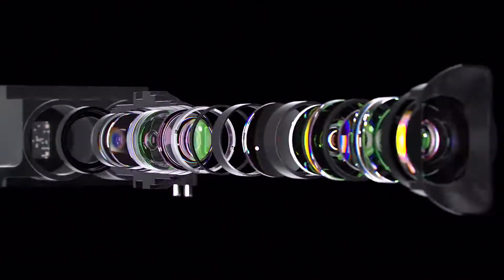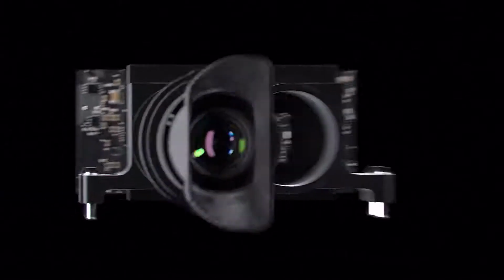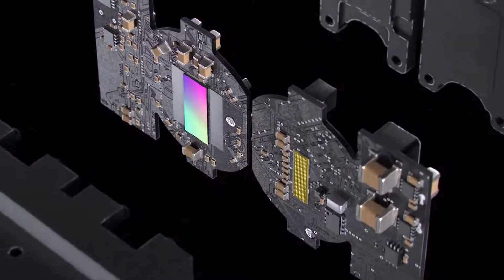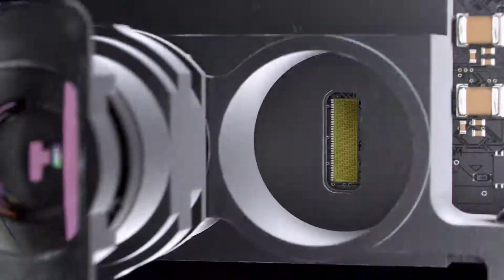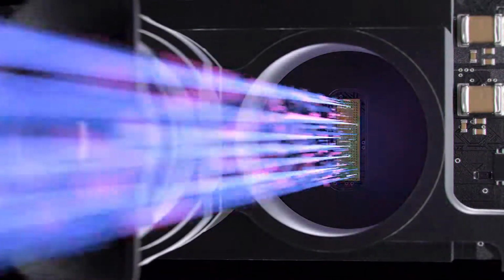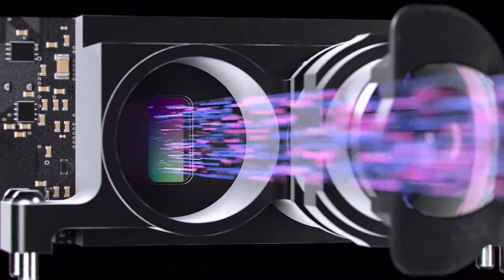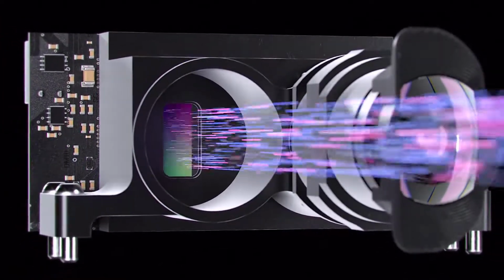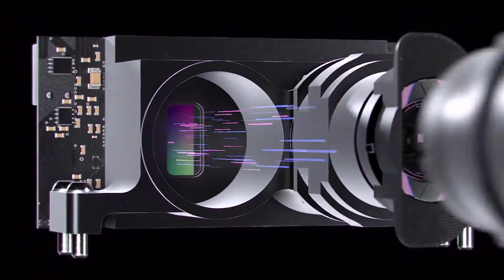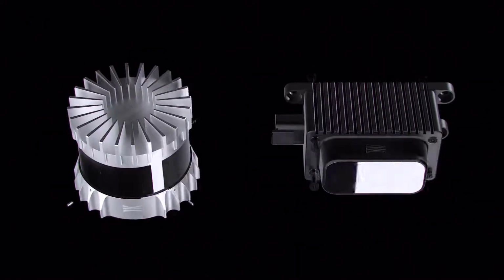Custom lenses that define the sensor's range and field of view just like a digital camera, a patented micro-optical system that increases performance by orders of magnitude, a high-efficiency laser array, which integrates all of our lasers onto a single semiconductor chip. Last and most important is our Lidar system on chip. This piece of silicon uses SPAD photon detectors capable of counting over 1 billion photons per second. Our digital Lidar architecture powers all of Ouster's products.